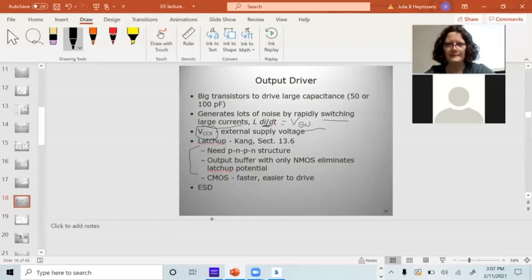Yeah, because I remember back in 490 you were saying, was it the little static shock when you touch door handles? Yeah, like 5,000 volts or something? When you touch a door handle and you can feel it, it's in the kilovolt range. A lot of these devices can be damaged by 50 volts or lower. So it's not just you feeling the ESD zap. There's a lot more low level than that.